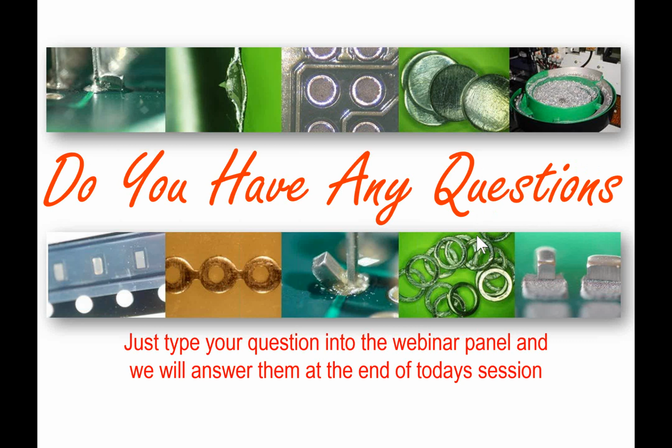I've seen components that have been produced, or connectors which have had pins connected to them, and they've reflowed, made a beautiful joint within the barrel of the hole where the pin went, but on the top where the original preform was, it hasn't completely reflowed. So it takes up the kind of misshapen shape of a preform.